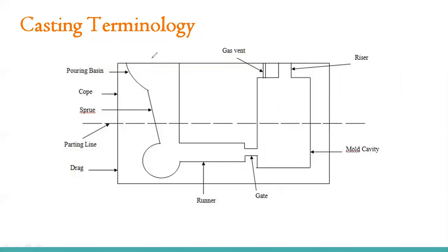Okay, so once the molten material from the ladle is poured into this pouring basin, as I said, sometimes we use this shape for the mold pouring basin. Once the molten material starts filling it, it will reach this height. As we are continuously pouring, it will start moving in this direction. So we can also say that for the smooth flow, we are using this shape of the pouring basin.